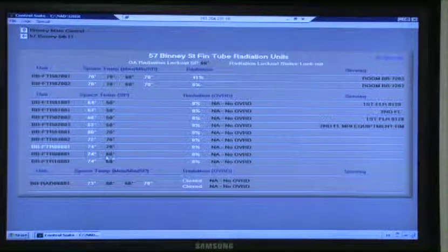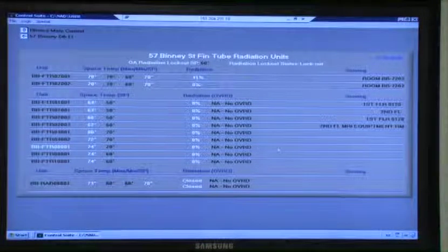Those also have low alarms on them too. Okay. I believe those, you'll get a low temperature alarm behind those. Can we get that? If there's an alarm, I think we need to have all those alarm set points. If it's a low alarm, tell us that it's a low alarm. You may not want to fool them, it's an isolated space, you may just want to leave them behind the scenes.